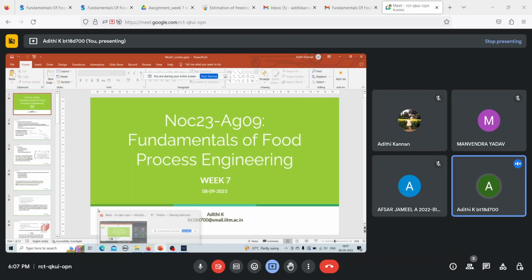Then it will circulate to the heat exchanger or a condenser heat exchanger where the air will be further cooled with the help of a refrigerant. And then this cold air will again recirculate inside the room. So blast freezing is a direct contact freezing technique where the air inside the room is cooled by a refrigerant, and this cold air is what freezes the food product, and it is not the refrigerant directly.